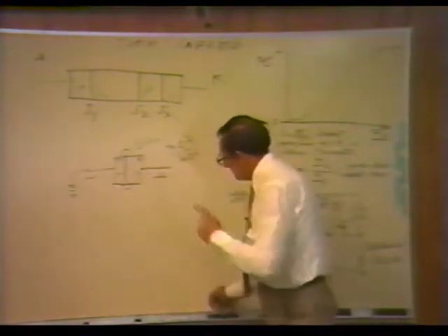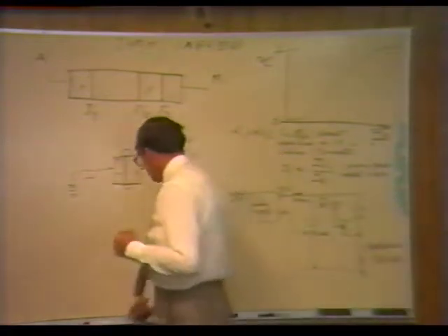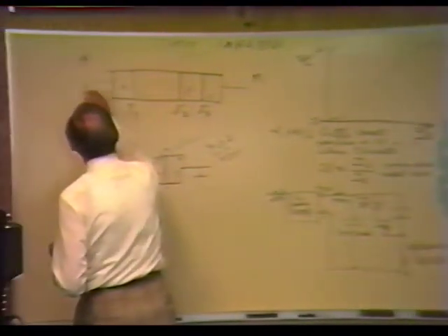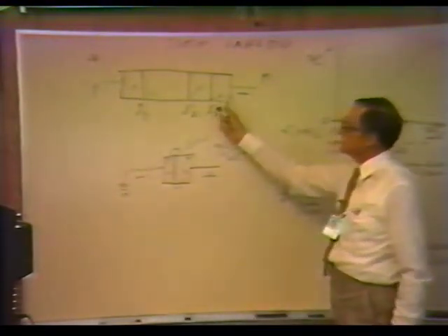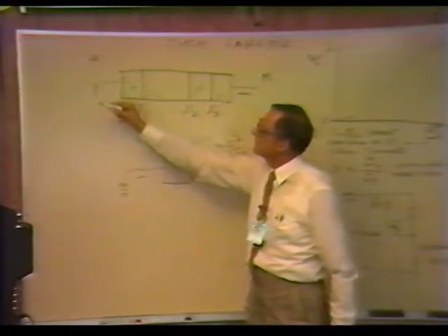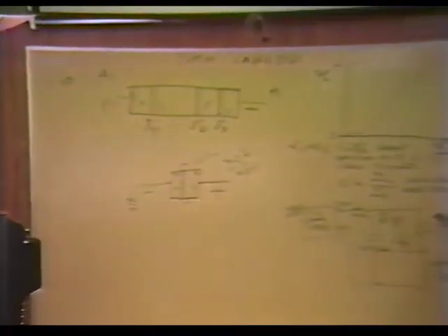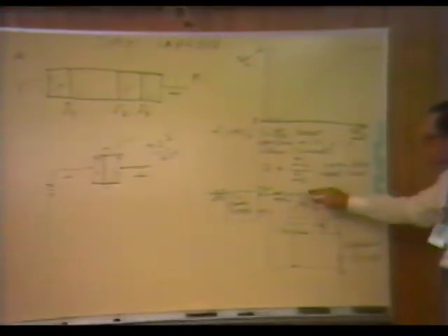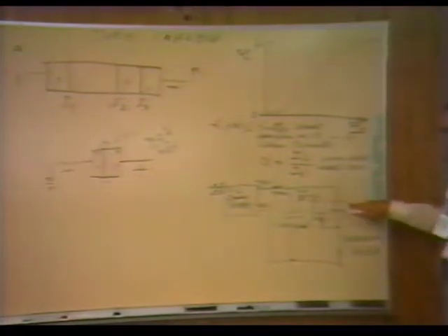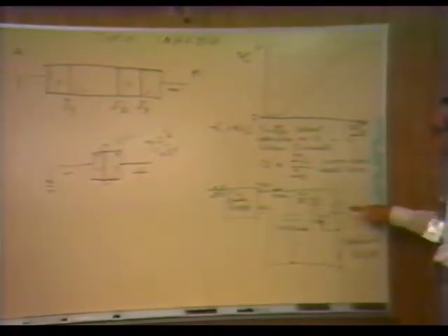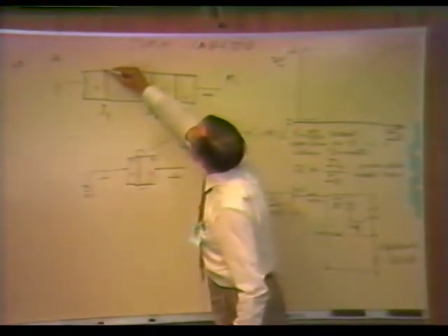Now, the way we hold off voltage in an SCR is just the same. We put a positive voltage here. And let's look what happens to the junctions. We put 30 volts here on the SCR. You want to keep that switch open. You don't want it to conduct while that's charging up toward 24 volts. In this case, I showed 30, but it's charging up now, and you want that to stay off, be a very high resistance. In the first place, now you have a PN junction that's forward biased.